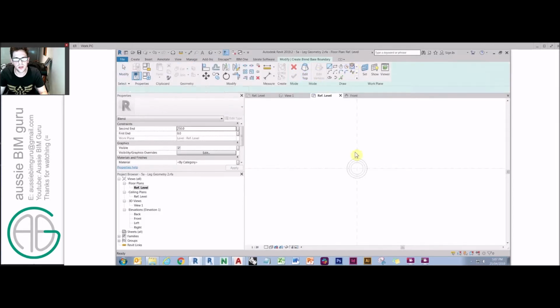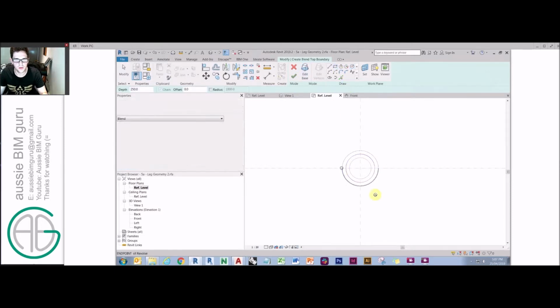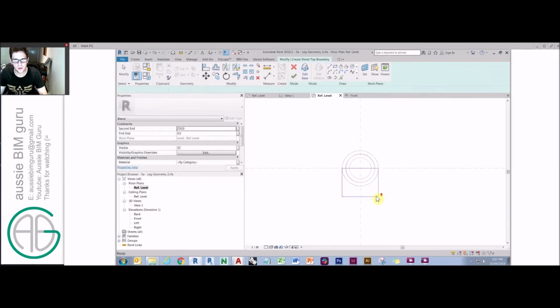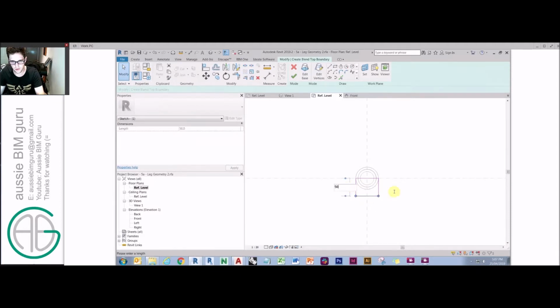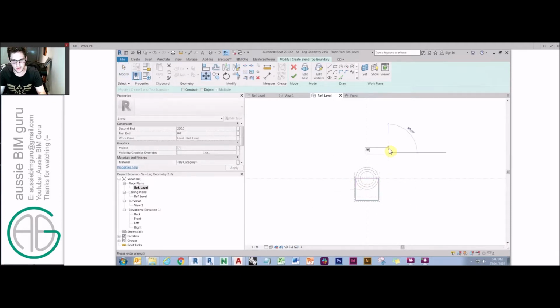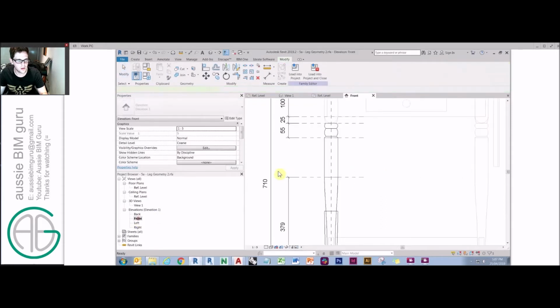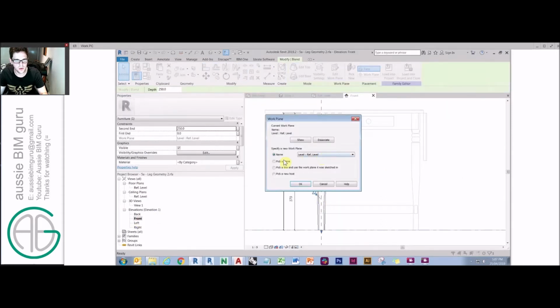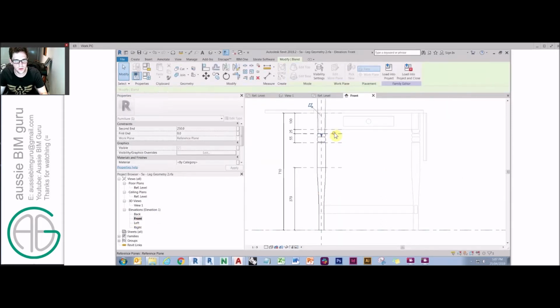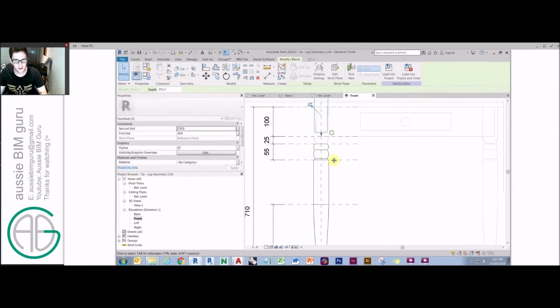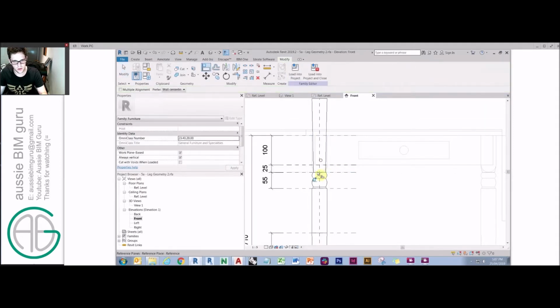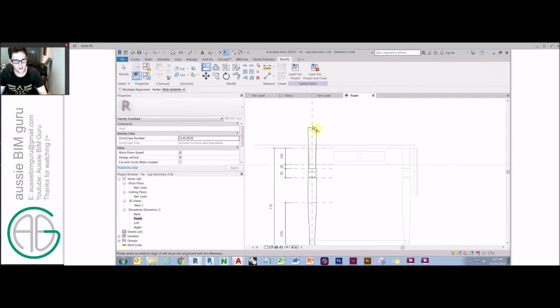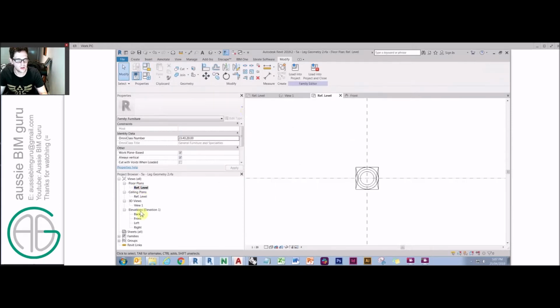So we're going to do our base, and we're going to do a 20mm base, and our top is 50 by 50. And I'll just position that after, and we'll center that on there. There we are. And we'll just change the work plane to here. And blends are quite easy because you can just lock their base like an extrusion once you've got those two profiles in place. Great. And then the last thing we need from there is another extrusion.